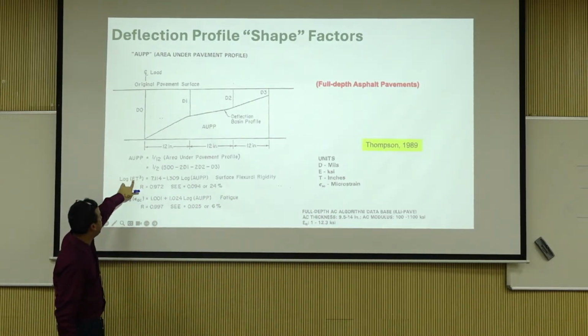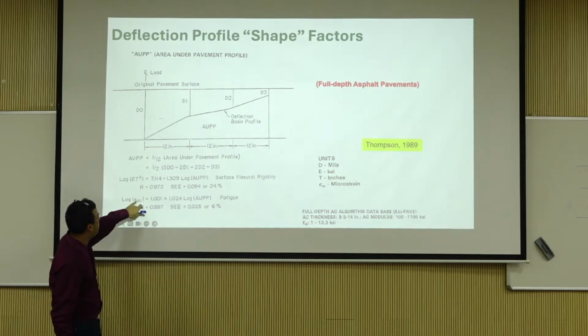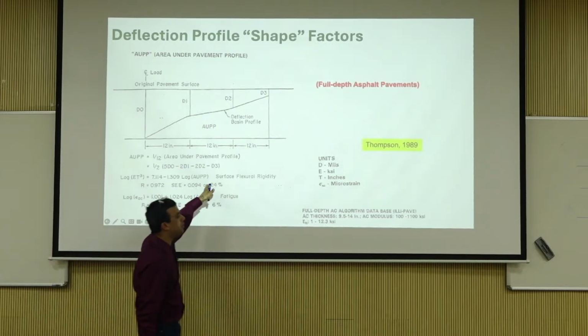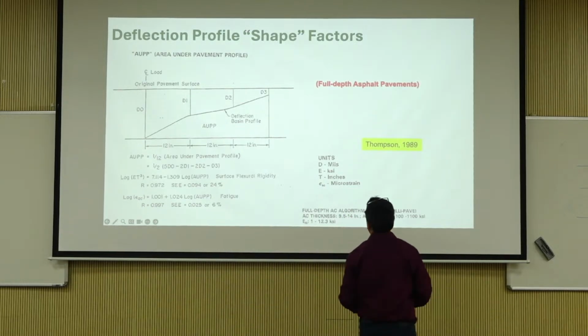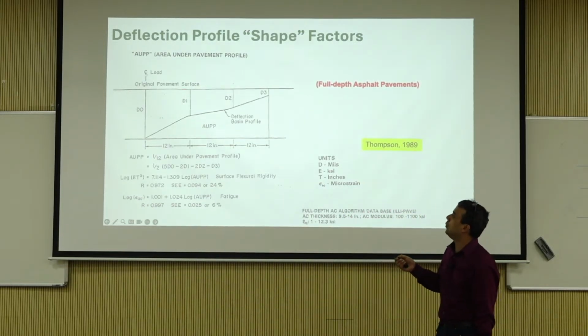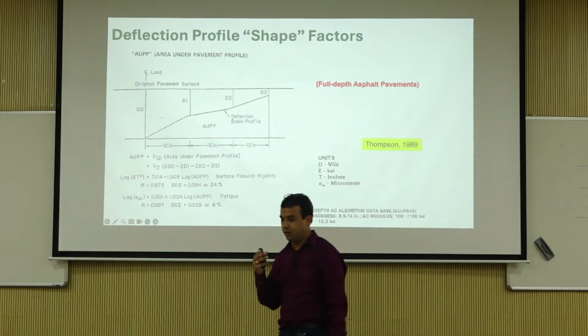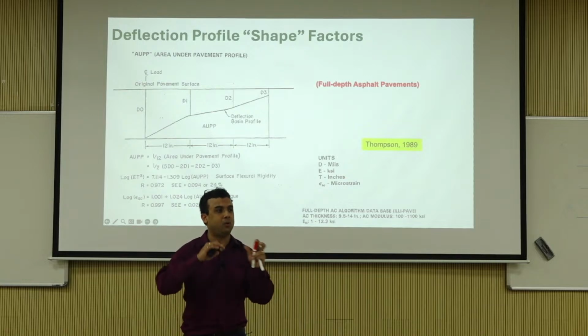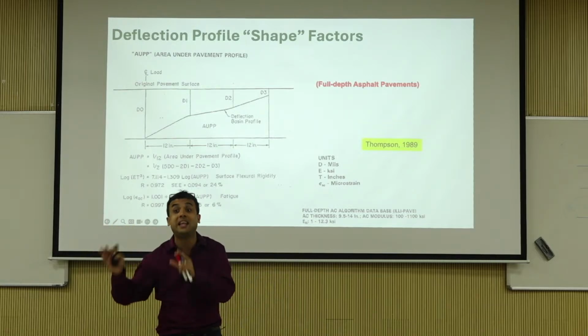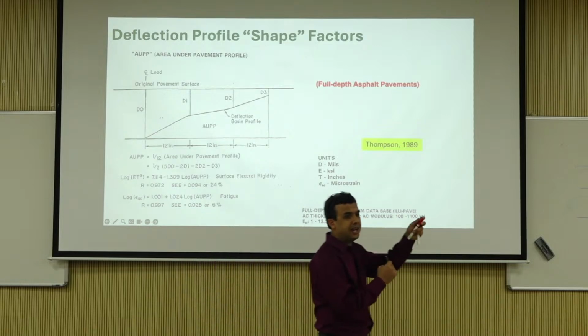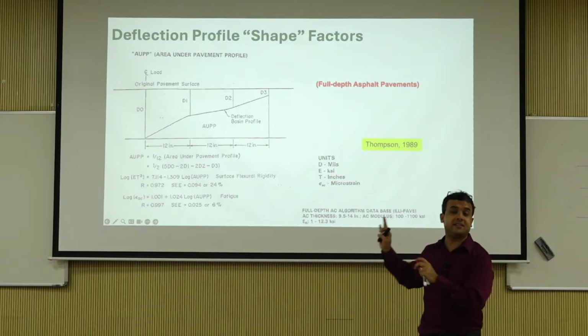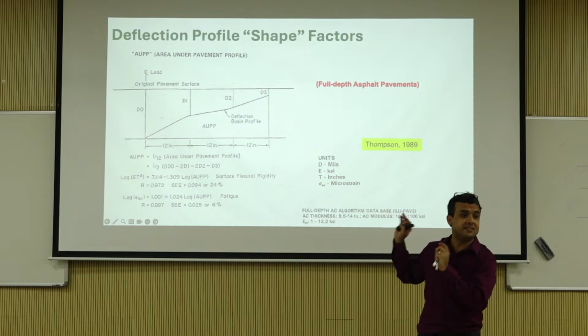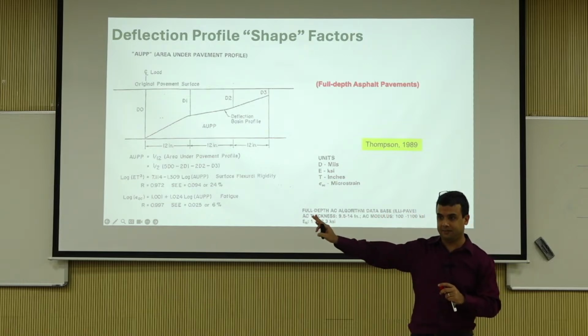asphalt modulus, which is log E multiplied by T cubed, thickness cubed, and epsilon AC, which is the horizontal strain in the asphalt layer. So this is all done mechanistically. If this is what your area or your FWD data is giving you, then you should be able to get some idea about what the strain and the modulus are, without running full-fledged back calculation. I am not saying this is a replacement for back calculation. I am saying this is an easier way of implementation, right?